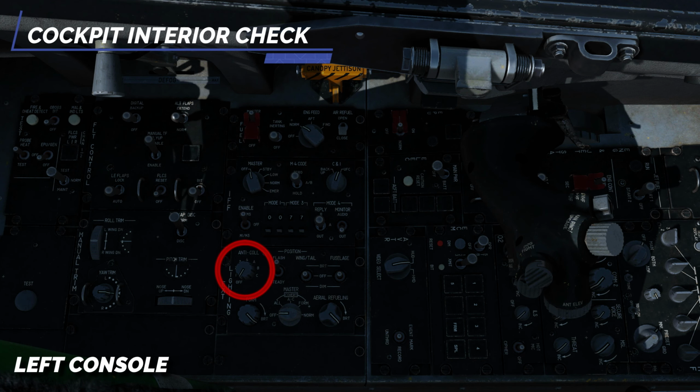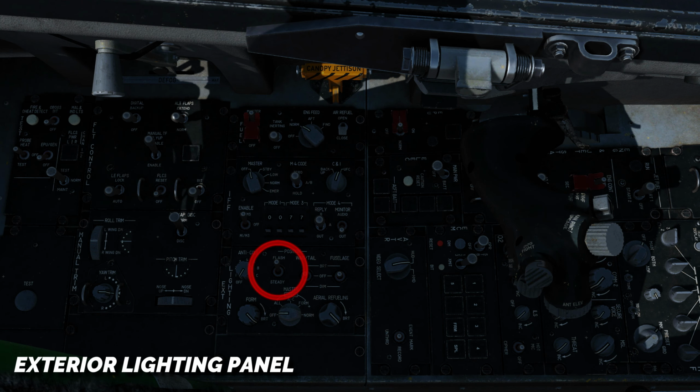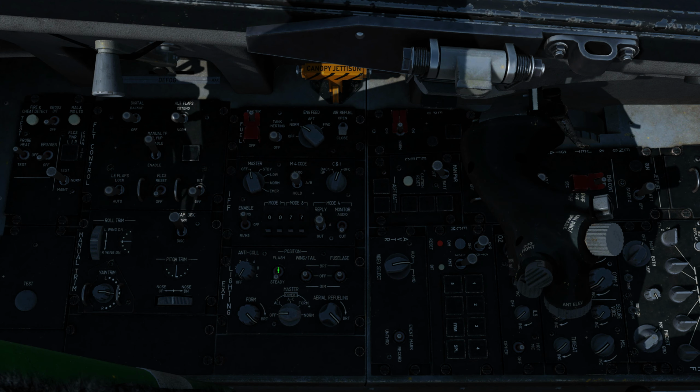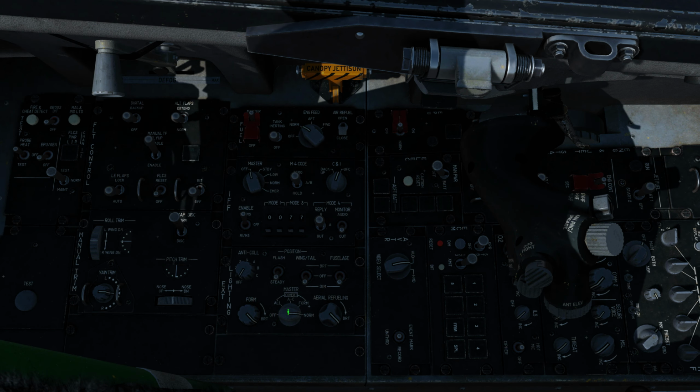Set the anti-collision light to off. As the aircraft is stationary, set position lights to steady. Set position lights to dim or bright with the wing/tail and fuselage switch. Set master light to normal. In this position, the aircraft lights will illuminate when the main generator comes online.